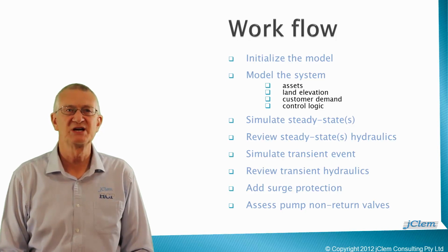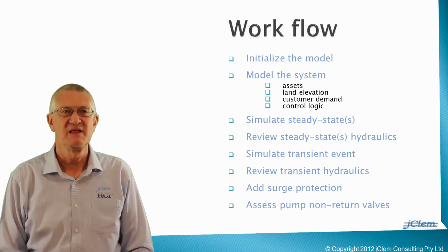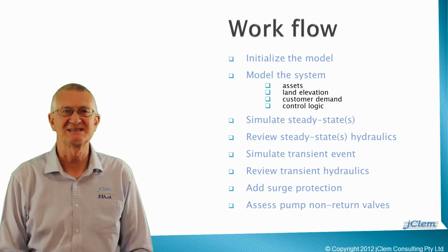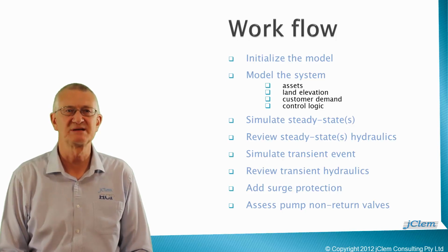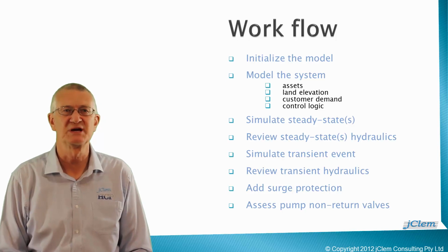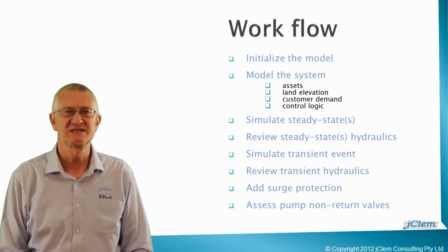You will start by initialising a model with its basic setup information. Then you will build the model by adding assets, land elevation data, customer demand parameters, and automatic control logic. These are the steps that take the most time. Then the interesting parts commence and happen quickly when you simulate and review the steady state hydraulics.